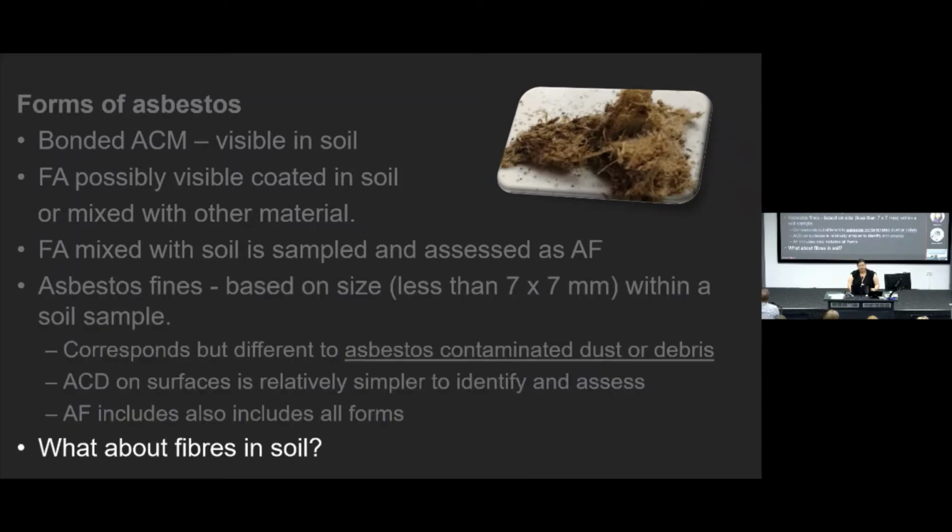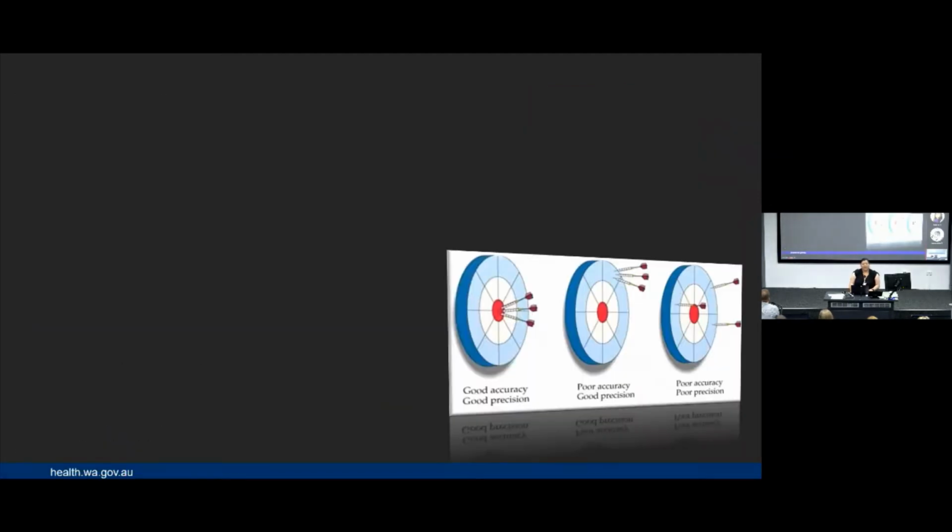What about fibres in soil? Well, we still don't have an accurate and accepted method for quantifying fibres in soil. There are ways that you can do that. The problem is that you can look at a very small amount of soil and be very precise about how much fibre is in that small amount of soil, but then how representative is that very small sample of your entire site contamination? So it becomes a really difficult interpretative mess if you're unsure about what to do in this state.